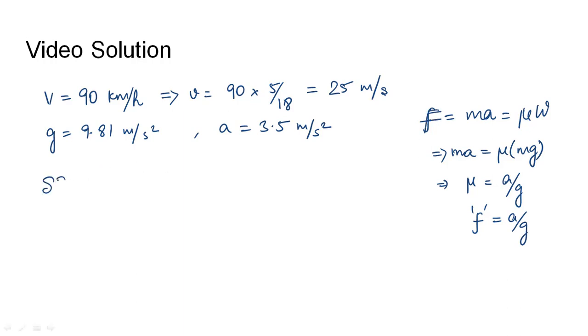So SSD, which is 140 meters for this problem, is equal to V times reaction time plus V square over 2gf.